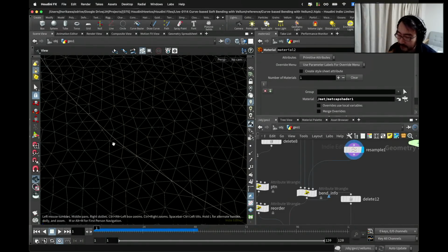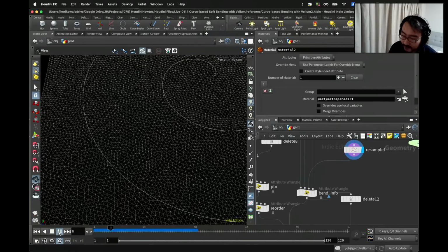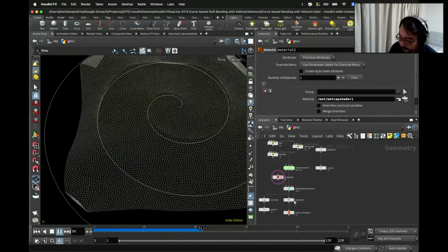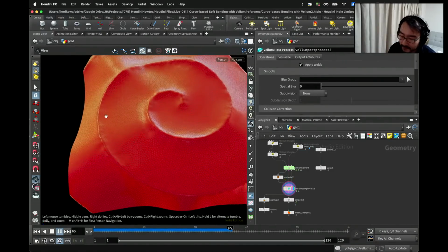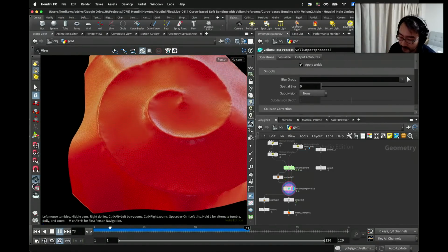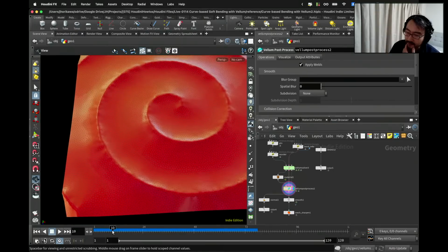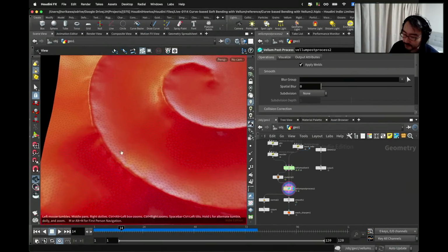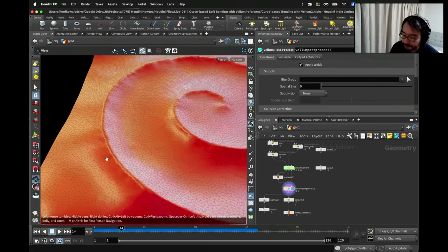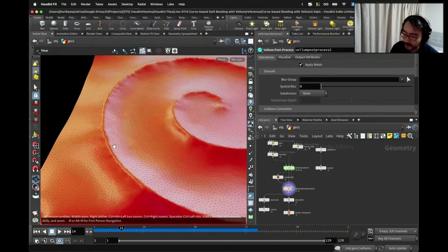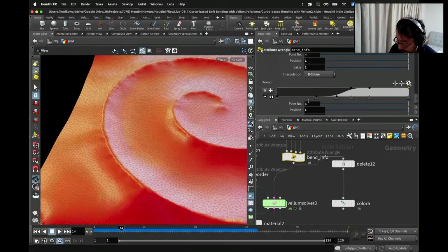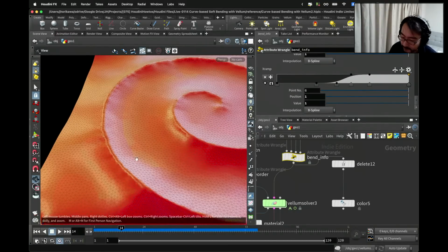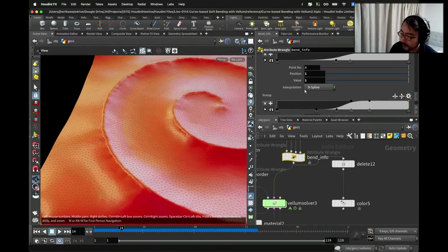And that's all you need to do in order to achieve bending simulations like this one. The downside is that you don't get a clean edge, but the benefit of using this one is that you could have a smooth folding on a specific area by controlling the threshold, like how much you want to affect the bending and what's the angle for each position.